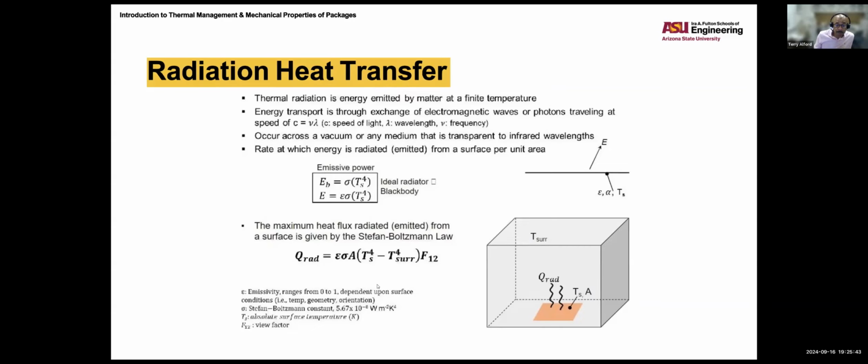So we put view factor F12, that's 1. Emissivity, 0.7. Stefan-Boltzmann constant. The area is given, 0.24 meters squared. And we do the calculations in Kelvin, and we get 374 Kelvin. We convert that to 101 Celsius. Okay.